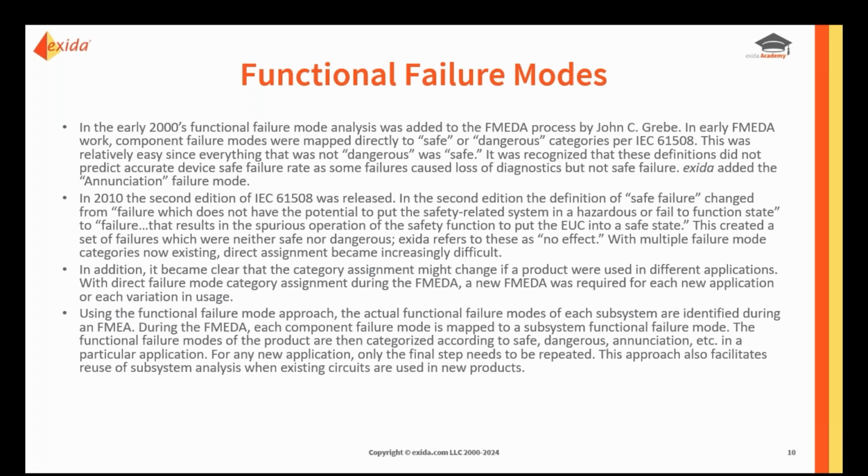So Exida added a no effect failure category to cover those failures that were neither safe nor dangerous. So now there are a whole bunch of categories, and direct assignment is getting harder and harder. And it's also getting harder and harder to modify FMEDAs.